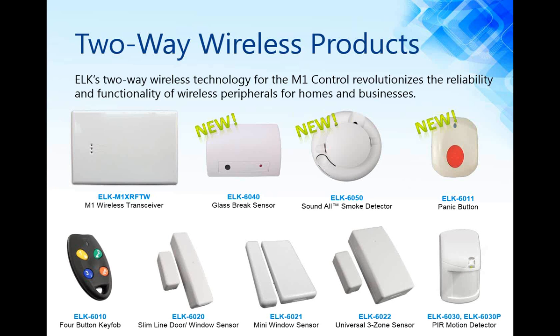Now on our window door sensors, our 6020, 6021, or the 6022, the LED will light green if it gets the acknowledgement back from the wireless transceiver that the signal was received. If it lights up red, the signal was not received. So it's a great troubleshooting tool also, to let you know if you're in or out of range of the wireless transceiver.